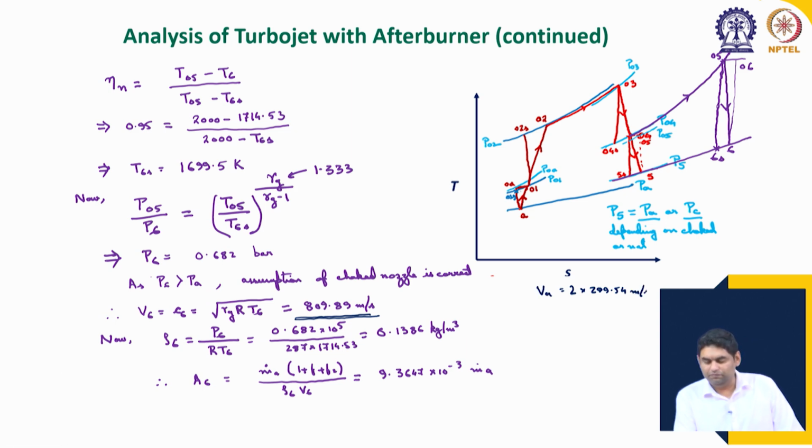So, this will still be less than the exhaust gas velocity. So, the convergent nozzle is still sufficient. Although it is limited to Mach 1, the aircraft velocity can go to Mach 2 also, because the speed of sound is different at different temperatures, and the exhaust gases are at a much higher temperature as compared to the ambient.